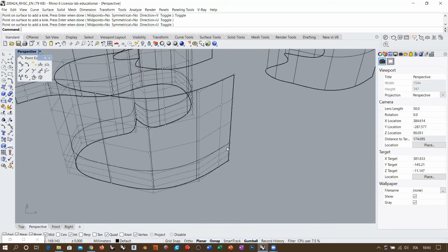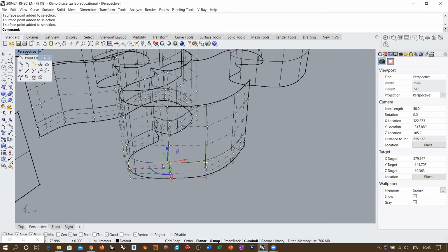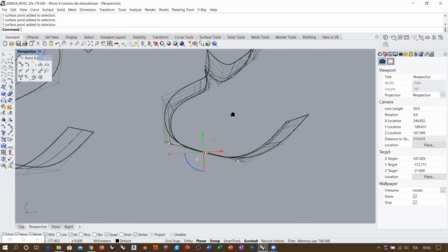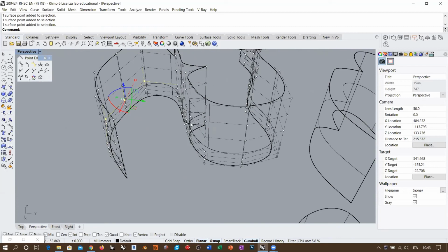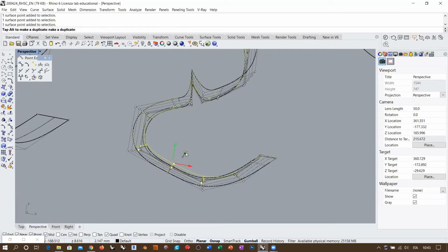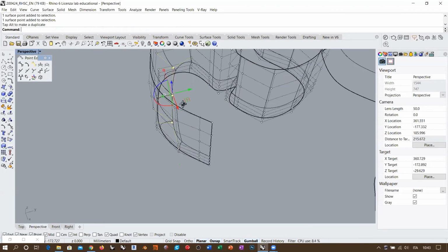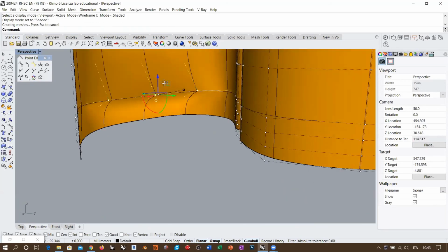But this time things work differently, because if I select all these control point lines, for example, I want to create some kind of kink deformation in this area, okay? So some complex modeling occurring here. So let's say that this is, for example, the inner part of a wardrobe, and I want to add a seat in this area, okay? So I create this kink line, and I take these 3 control points here, move them inside, and I am creating this kind of, let's see it with shaded, creating this kind of situation here.